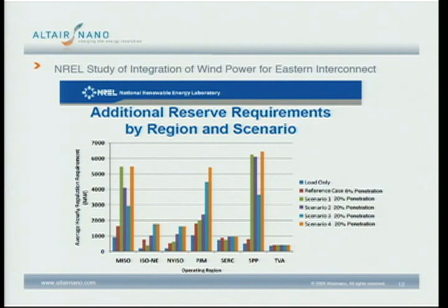And I don't think I included it, but out of the California study, right now we're at about 300 to 400 megawatts of regulation. To go to the 33% RPS, they're looking at around 1,200 megawatts of regulation to as much as 4,000 megawatts of regulation during ramping periods, during shoulder months when there isn't as much hydro, when there's a big differential between night and day temperatures, when there's a lot of dynamics to the energy system in California. And that's a big number. And that's a number that we're all paying.